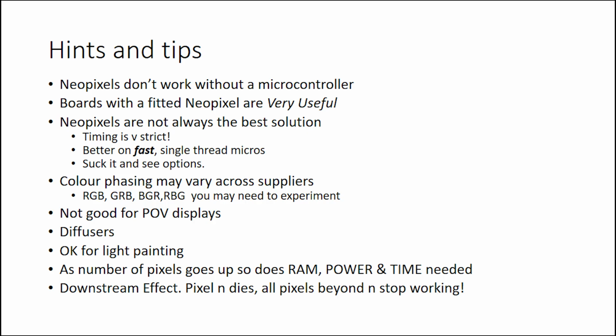Because of timing, and being strict, NeoPixels might not be the best solution for what you're trying to do. They need a fast, single-threaded micro, in my opinion. You need at least 16 megahertz. 32 megahertz is better. The ESPs and all that now run at 75 megahertz. The top-end PICs run at 72 megahertz. The one thing you also have to worry about is dividers.